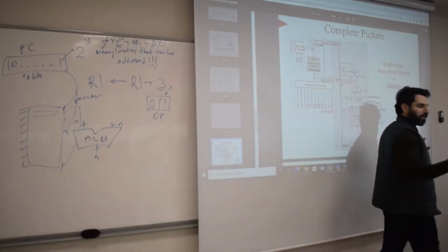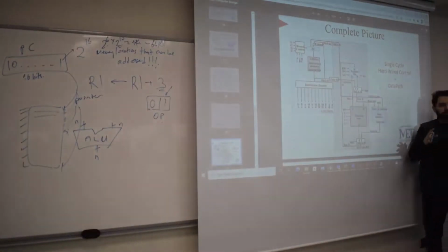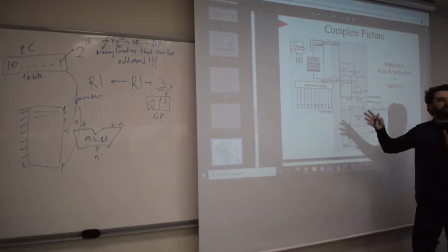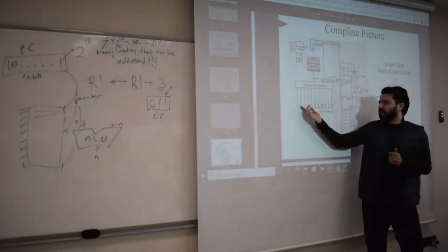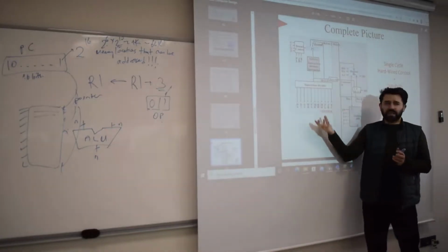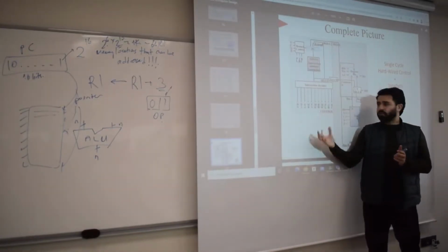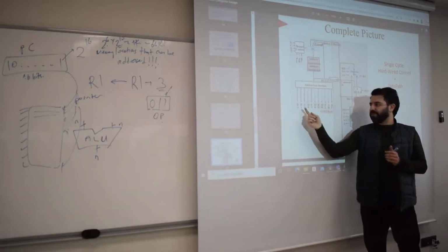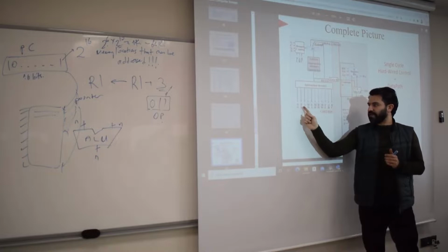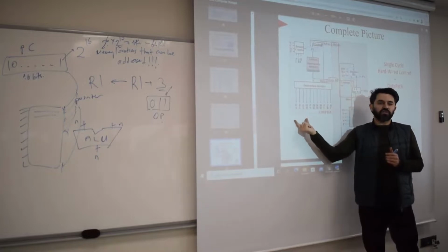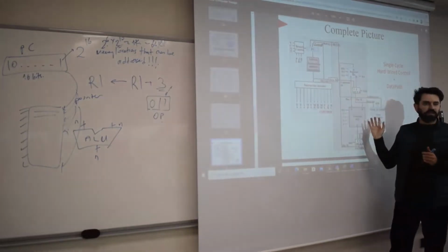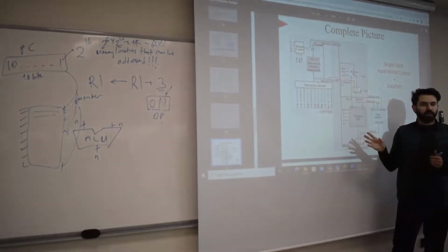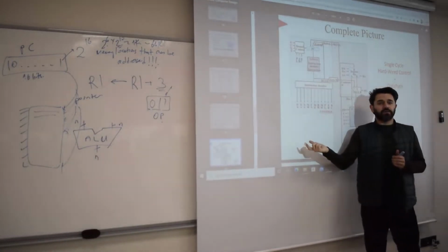But multi-cycle is also very similar, because now you distribute all this stuff over multiple cycles. For example, how are you going to send those control bits? It's easy. You just delay some of them, okay? You can actually put in some registers. For example, if you put this DA, BA, AA into a 9-bit register, and these are all connected immediately, but that goes into a register, and then from the register to the corresponding locations, well, that will put in a delay, right?